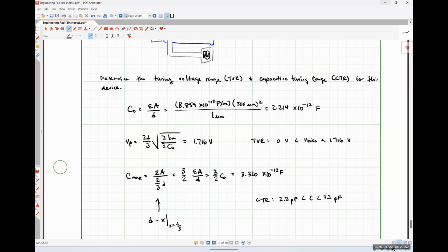And they were using it for voltage controlled oscillators, I believe, if I'm remembering correctly from my lit review I wrote for my PhD a decade ago at this point. But they tried all sorts of things, like trying to figure out how to effectively manufacture beams underneath to keep the plates from snapping and closing together, so that they could get a little bit more tuning range out of it. All kinds of weird little things like that.